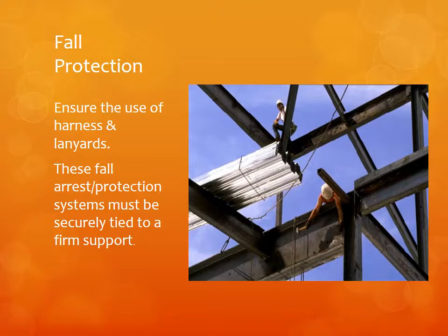On a work site, your objective should be zero accident. And in achieving zero accident, you must ensure that your workmen comply with basic safety procedures and basic safety requirements. At the minimum, make use of fall protection equipment and fall arrest systems, so as to prevent or mitigate the risks of falls that they are exposed to.